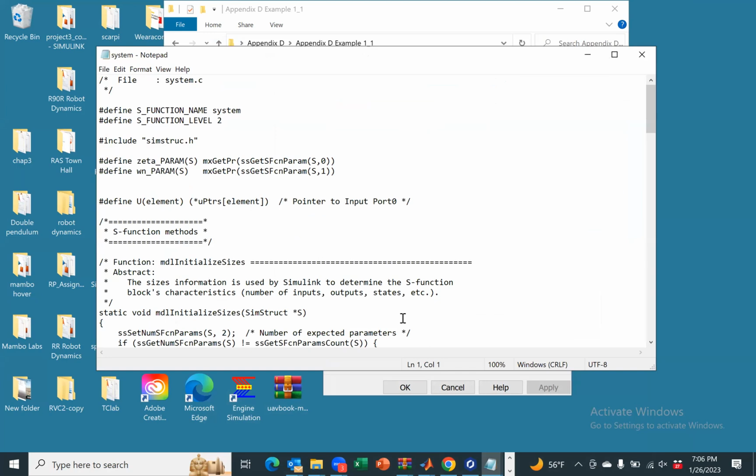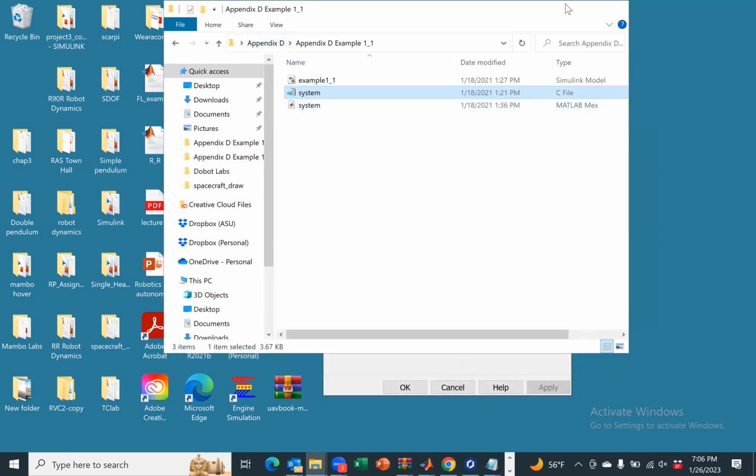So for an example, if you have this C code, this is very, very useful because you can have a C code that is running on an embedded system, put it inside MATLAB, and wrap it around the S function, so you can simulate how that embedded system would behave, and the code snippets remain the same. So you know how it will behave in the MATLAB environment. You can make modifications. You can add some MATLAB toolboxes, some MATLAB signal processing, and then get the results that we are looking for. Everyone understood this? I'm not going to explain this, but it is given in the textbook very nicely.